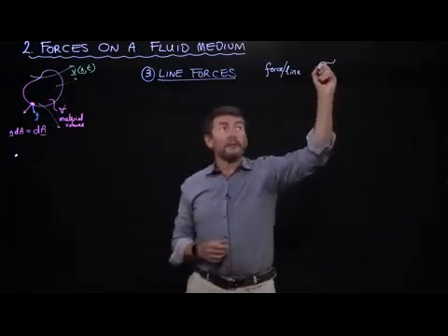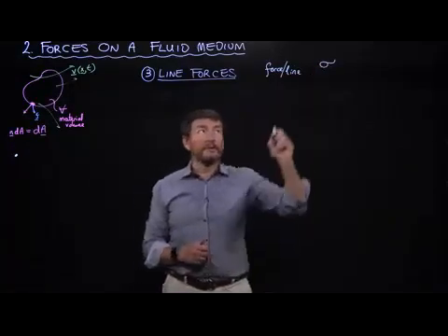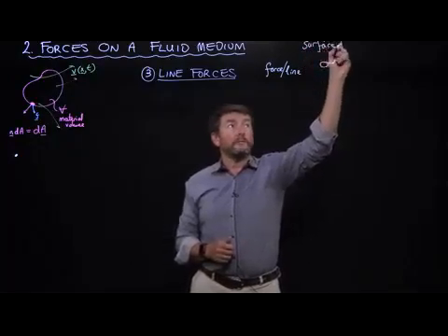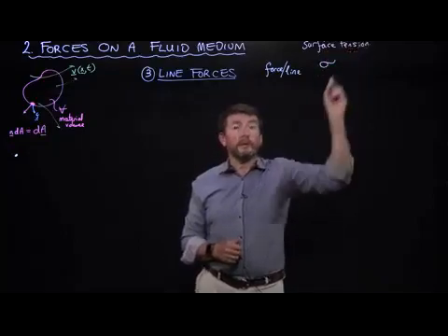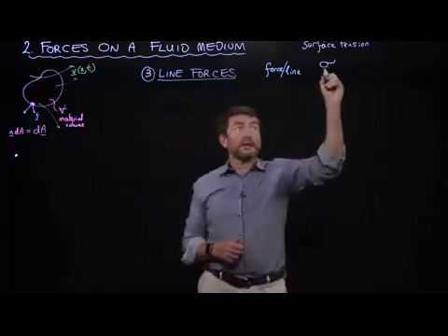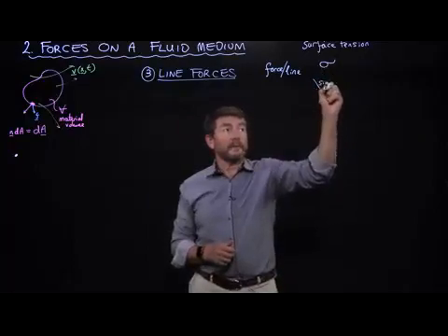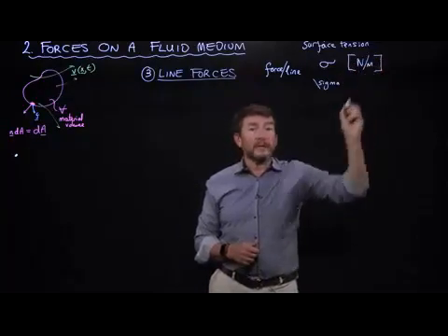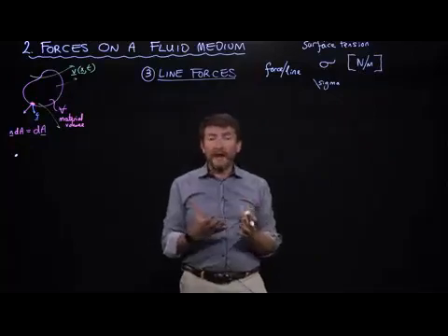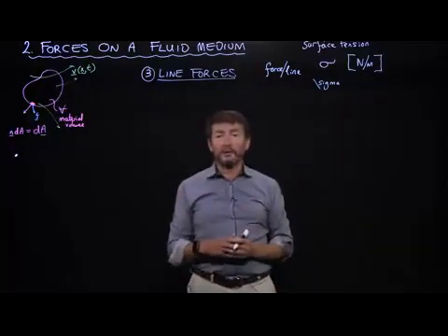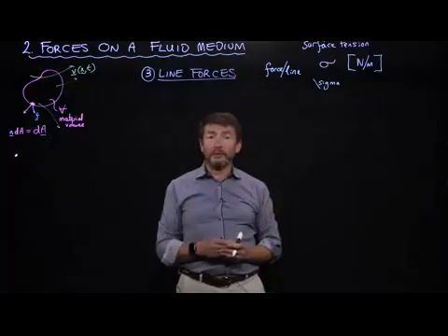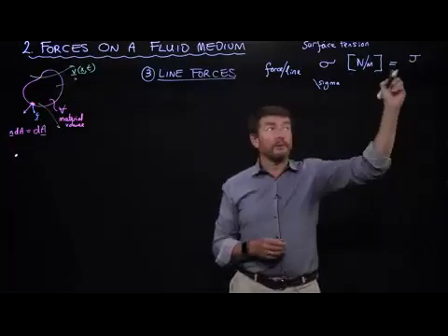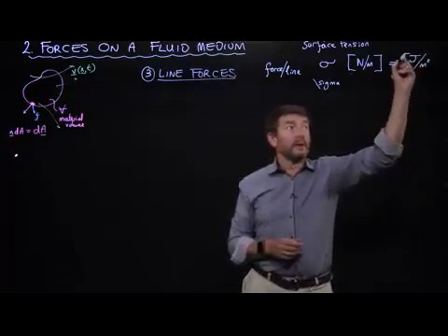The most common example of one that we'll see in fluid mechanics is usually given the symbol sigma, and this would be what people would call the surface tension of a material. The SI units of it are newtons per meter. But the right way of thinking about it is it's really the energy that's required to make a unit of surface with a given area A. And so if I think about it that way, then I can also think about this as having units of a joule, which is a newton times a meter, divided by meter squared.